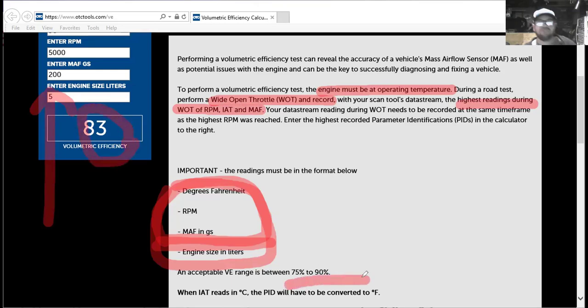Well, as it says here, most cars these days are between 75 and 90%. And I said really between about 80 and 90%. And so why is this valuable? Well, because if your engine doesn't come out between 75 and 90%, that's telling you, hey, something's wrong. Now, it could have a restriction. If I had a really restricted air intake or a really clogged up exhaust, like I had a plugged muffler because the catalytic converter started to fall apart, all those things would make this number go down. But you know what's more common than both of those?